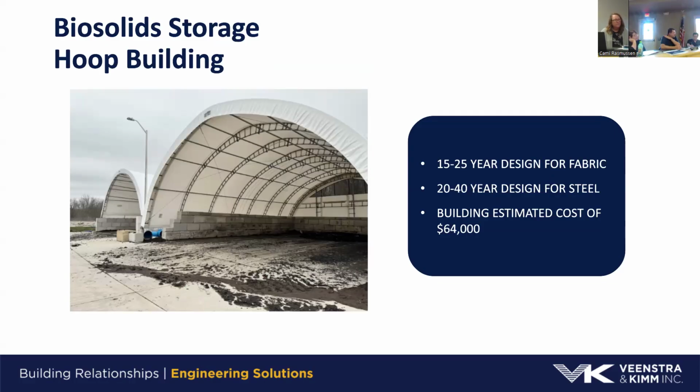What do we do with the biosolids? Is this a cycling thing? So biosolids have to be hauled off. Most towns land apply them, so they'd have one of the sludge haulers come out and land apply them. But obviously, when they're land applied on farmland, there are only certain times of the year that you can do that and be in the field. So that's where that 180 days of storage comes from. You have to wait till the crops are out, or you have to wait until spring where it's dry enough that you can get on the field, but before they plant. So spring is usually a pretty difficult period to hit.